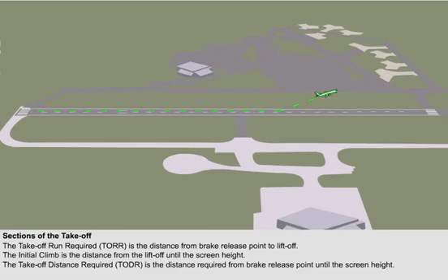However, in commercial transport, the performance is not measured in terms of the takeoff distance, but rather in terms of the weight that can be carried. A good performance in terms of a commercial flight would be a takeoff with a large weight, whereas a poor performing aeroplane would only take off with a small weight. As a general rule, any effect that would cause the aeroplane performance to reduce would cause the aeroplane takeoff distance to increase and/or reduce the takeoff weight.